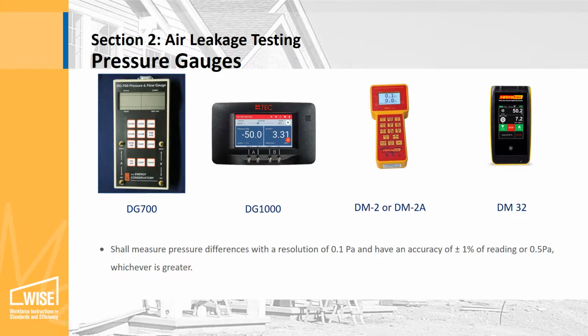The pressure gauges need to measure the pressure difference with a resolution of 0.1 pascals and have an accuracy of plus or minus 1% of the reading or 0.5 pascals, whichever is greater. There are several types and manufacturers to choose from. The most common are listed here from the Energy Conservatory and Retrotech.